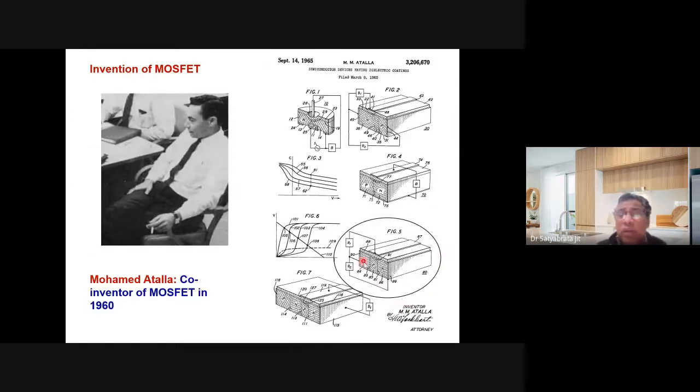What he did here: it was an N-type semiconductor, P-type semiconductor, N-type semiconductor, right? And over these, the entire region that he considered here was an oxide region, and in this case this was a metal, that is the gate, right? And this N type was connected by a metal, and this N type was connected by a metal. Clear? So NPN, the one side is used as the source, another side was used as the drain, and that was used as the gate terminal, right?